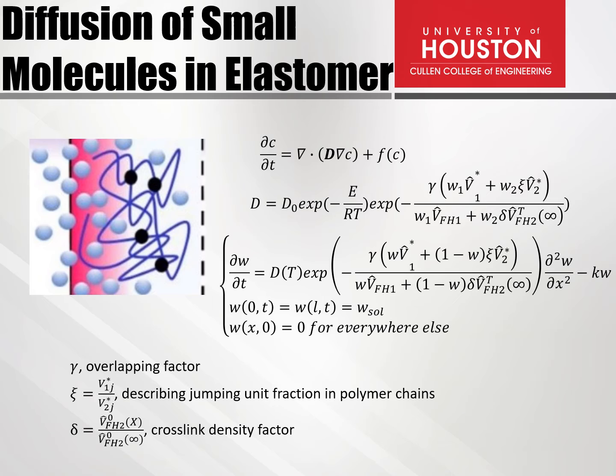However, the diffusion coefficient of small molecules inside cross-linked polymers is no longer considered constant. It is basically a probability of diffusant jumping frequency from its original position to the neighboring free site. Obviously, with larger hole free volume per unit volume, we can expect a greater diffusion coefficient. I'm not going to discuss in detail the diffusion coefficient in free volume theory here.